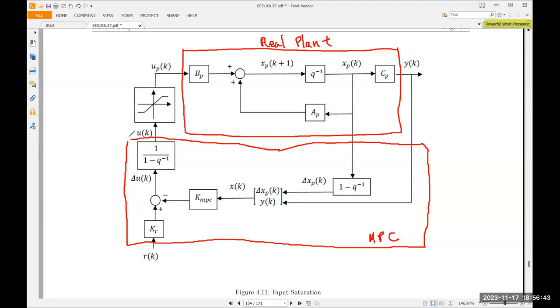All right, but actually in the real plant, there's a valve that chemical flows in, and there's a real constraint. When the chemical flows in, you open the valve, it's fully open, that's the constraint. You increase U further, the valve cannot open more than fully open. All right. So what if you do not consider that in the MPC calculation? What will happen? Your MPC will calculate U as though there's no constraint.